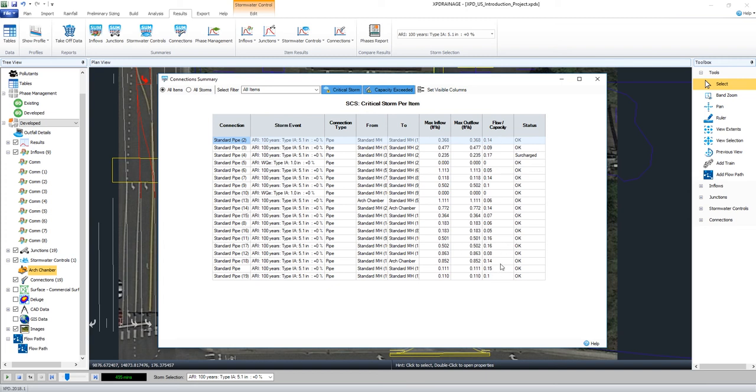That's an indication of how well water is moving through these pipes, in this case, versus what the Manning's equation capacity full flow would say should be allowed. In this case, the pipes perhaps are a little oversized. So you see we're well below 0.8 or even 1 in this flow divided by capacity relationship. So we have water really well flowing through our network.